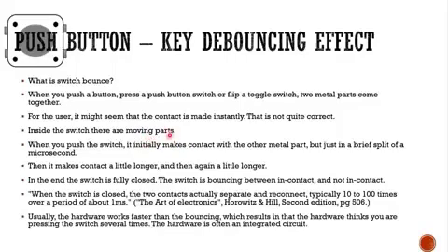Why? Because of the moving part. When you press a switch, it will initially make contact, but for a brief period of time it will stick. This means that you will connect, disconnect, connect, disconnect for a few microseconds. So what is the correct number? From the reference shown here, typically the number of contacts that happen is from 10 to 100 times.